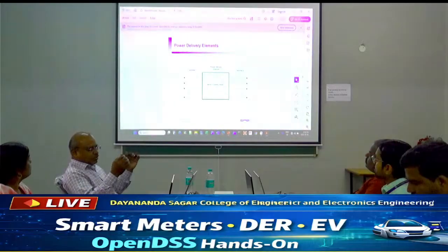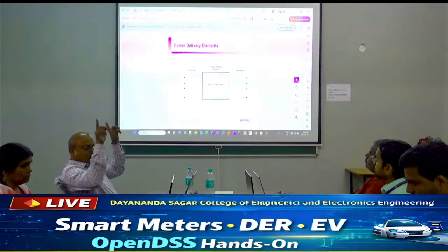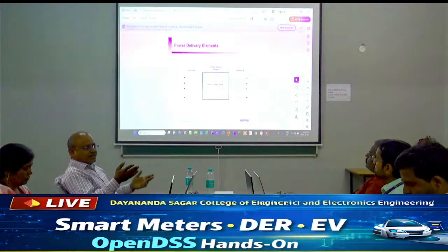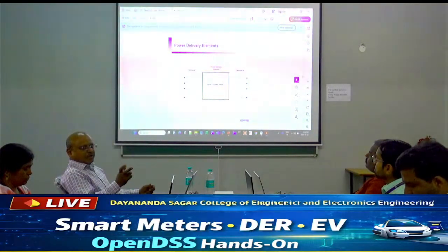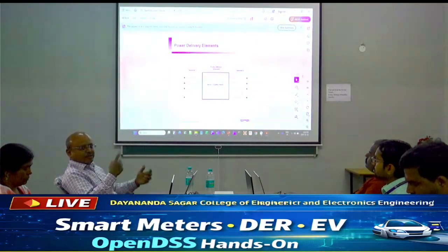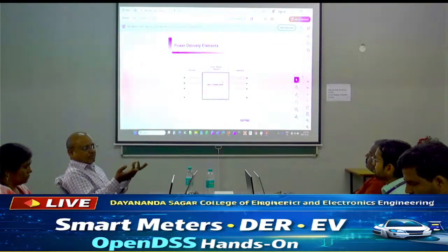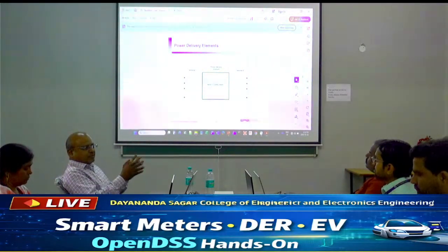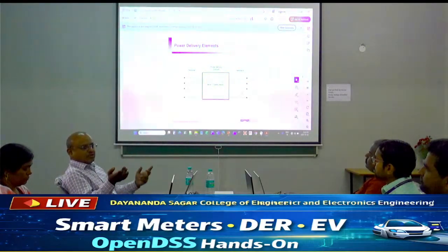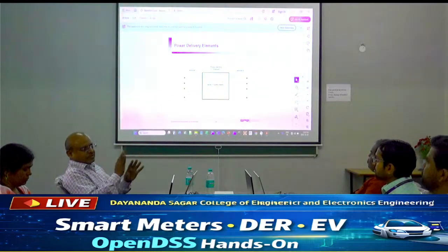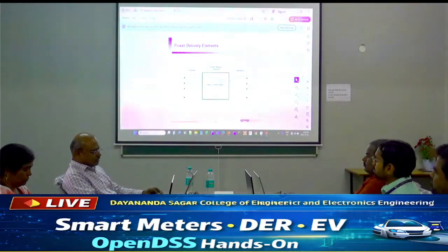Then using that it builds the whole matrix for the entire circuit as a sparse matrix, and then it uses the KLU solve library to solve the entire matrix. So it has two methods of solving. One is what is called the normal method, where it uses the K-solve. The other one is called Newton-Raphson. You can choose either of them, and then it will do multiple iterations for convergence. That is how it works.